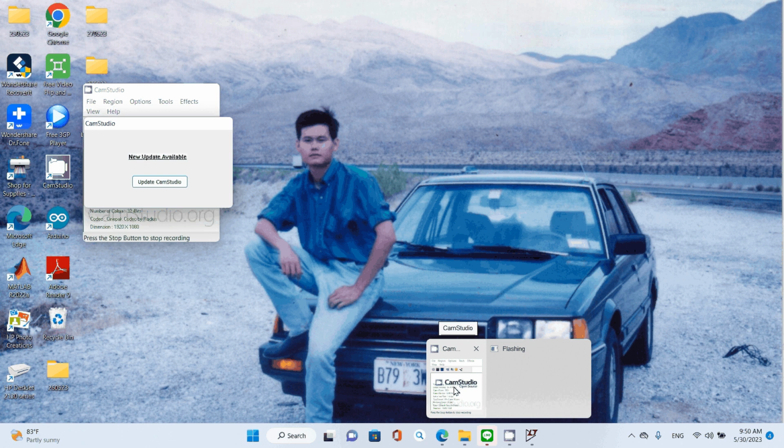You simply right click on IR1 here, and you see attach cursor. You go for just first and second. You click OK. Now you have two cursors active here. You move for one. Okay, you can see this is cursor number 1 and cursor number 2.